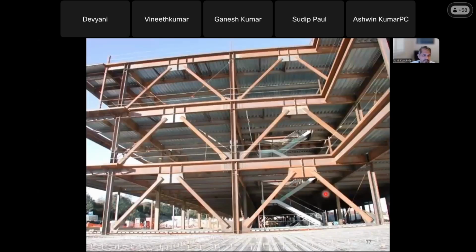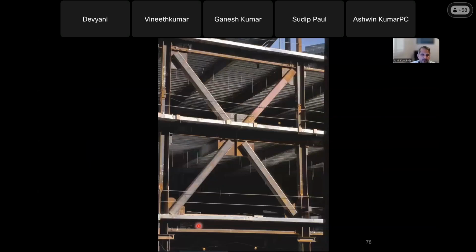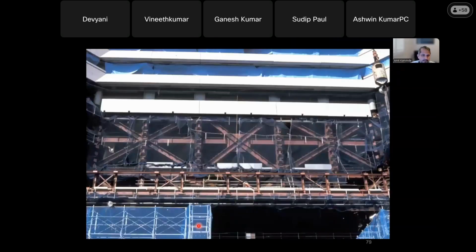Here's what a CBF looks like in the US. I do want to make another point: if you look at this entire building, you only see a CBF in this plane, and there are probably CBFs back somewhere there. This highlights that because these are designed to be ductile, you design them for a low force, and so you don't need a CBF in every bay. For example, these columns you're seeing in the back are not even seismic columns, they're gravity columns. Here are more CBFs showing different configurations.